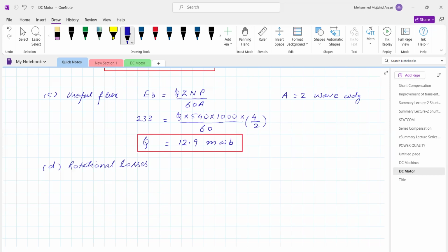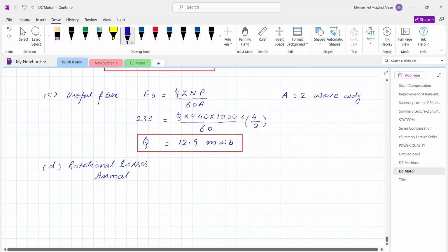So we calculate the armature input. We are just omitting the field calculation. So V into IA, which is the supply voltage 240 multiplied by the armature current. So it is 12,000 watt.